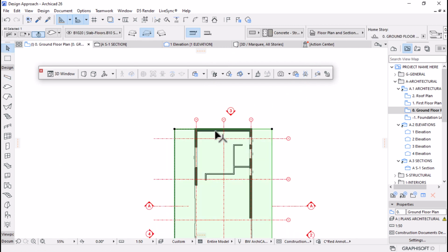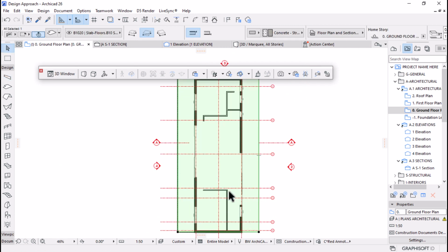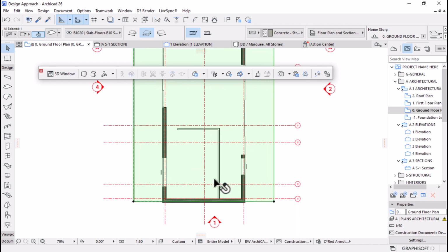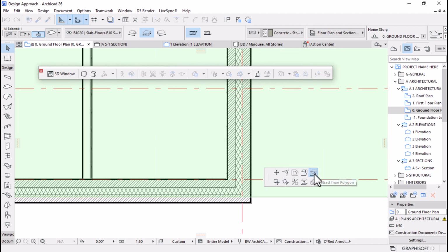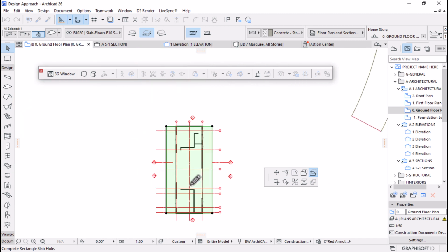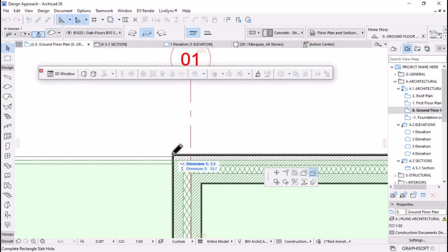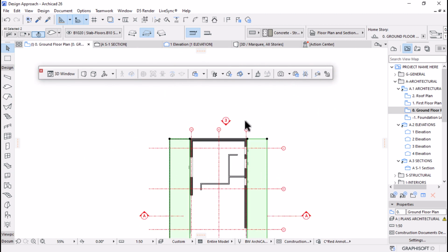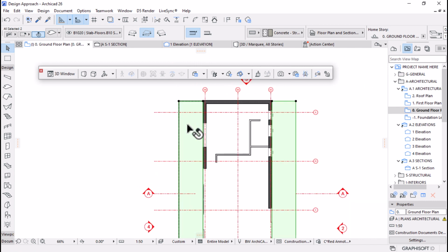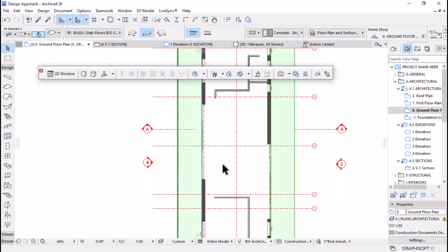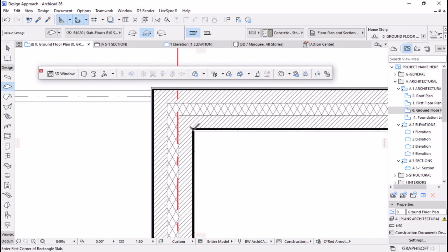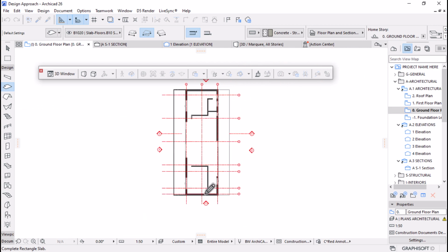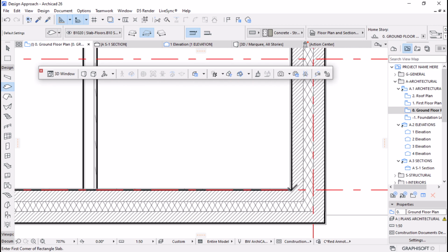Okay, and then the levels are going to be different for our floor finish. The floor level for, let me just separate this. I'll use add polygon to cut like that, so that I can separate these two. These ones are going to be on a lower level than the one on the inside, to avoid water spillage and such issues.